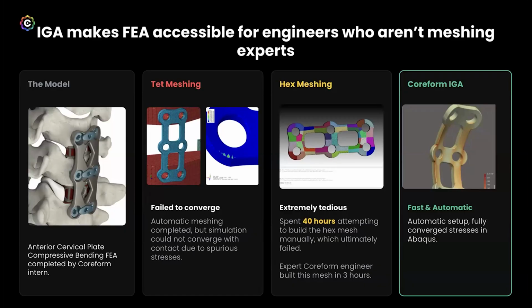The meshing was automatic and simple, but when she then ran the simulation, she had challenges with some spurious contact stresses. And we were able, with my assistance, to get this simulation to end up running. But again, that took someone who has experience running FEA and especially nonlinear to be able to recover those solutions.